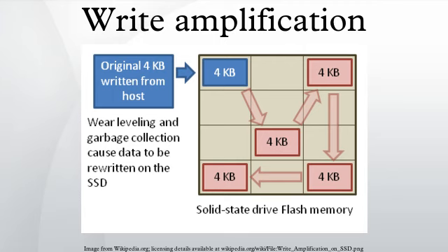Impact on performance. The overall performance of an SSD is dependent upon a number of factors, including write amplification. Writing to a flash memory device takes longer than reading from it. An SSD generally uses multiple flash memory components connected in parallel to increase performance. If the SSD has a high write amplification, the controller will be required to write that many more times to the flash memory. This requires even more time to write the data from the host. An SSD with a low write amplification will not need to write as much data and can therefore be finished writing sooner than a drive with a high write amplification.